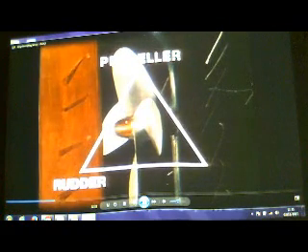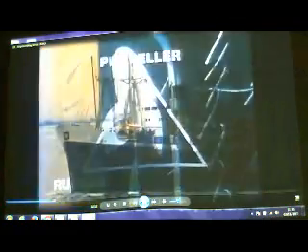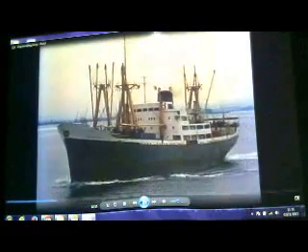What is the effect of interaction between propeller and rudder? When running ahead, the propeller accelerates a body of water astern, shown by the ship's wake. In addition, it gives the water a helical motion, seen when the propeller is close to the surface. This helical flow alone will not give rise to a transverse force. But what effect does the flow have on the rudder?